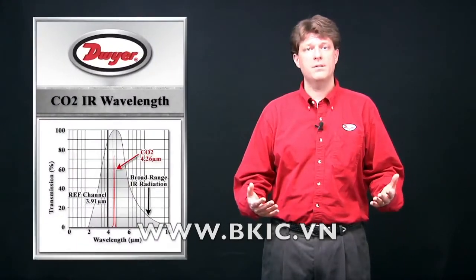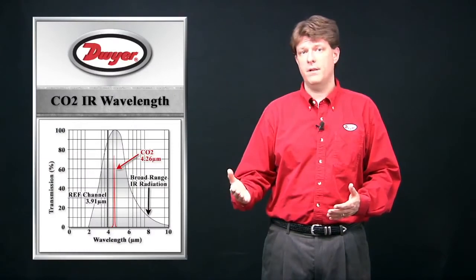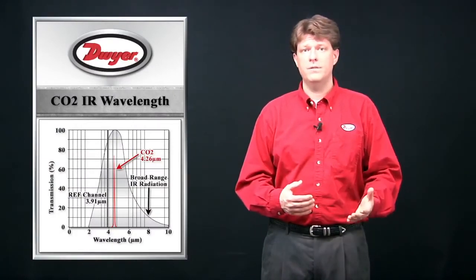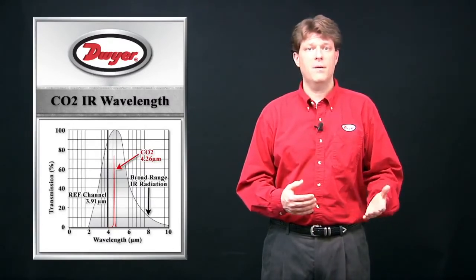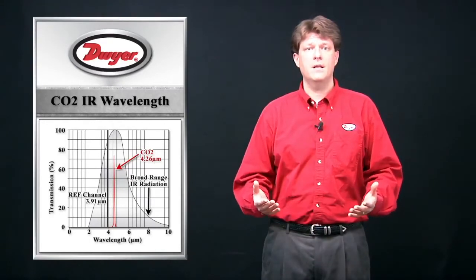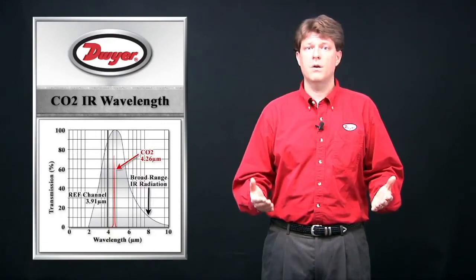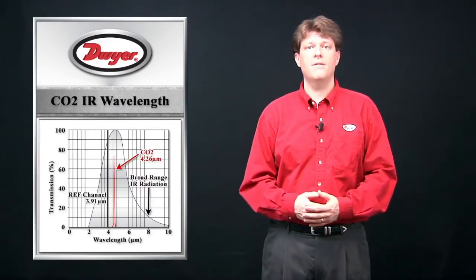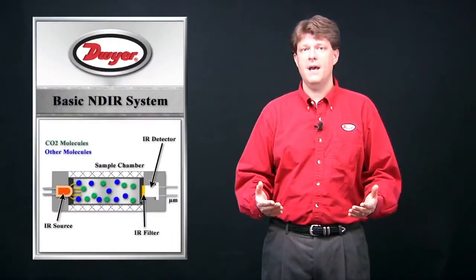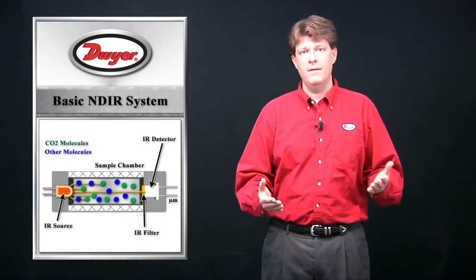NDIR sensors are based on infrared spectroscopy, the principle that molecules absorb specific light frequencies that are characteristic of their structure. When the frequency of the infrared light is the same as the vibration frequency of a bond, absorption occurs. Infrared light absorption of a particular frequency or wavelength creates a signature for conclusive identification and analysis of the gas and concentration level. A basic NDIR sensor consists of an infrared light source, a sample chamber, an infrared filter, and